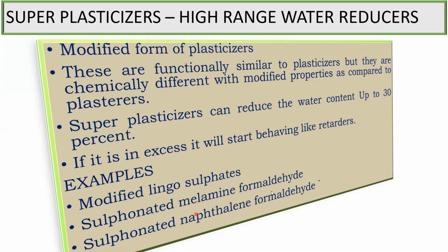Now again, coming to the examples, modified lignosulfonates are an example for the super plasticizer. Sulfonated melamine formaldehyde is an example for the super plasticizer. Sulfonated naphthalene formaldehyde is an example for the plasticizers, right?